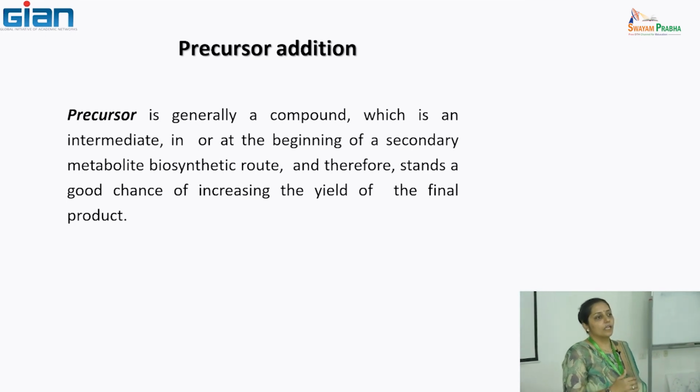The next step is talking about the yield enhancement strategies. Now, mostly for the media components, the response which you would take is two dependent parameters. One was biomass and the other was product content. If it were a growth associated product, I could have taken only a single response, which was my product titer, because it had both the biomass component as well as the product yield. Because it is growth associated, there's a good chance anything which is improving growth will also improve my product.